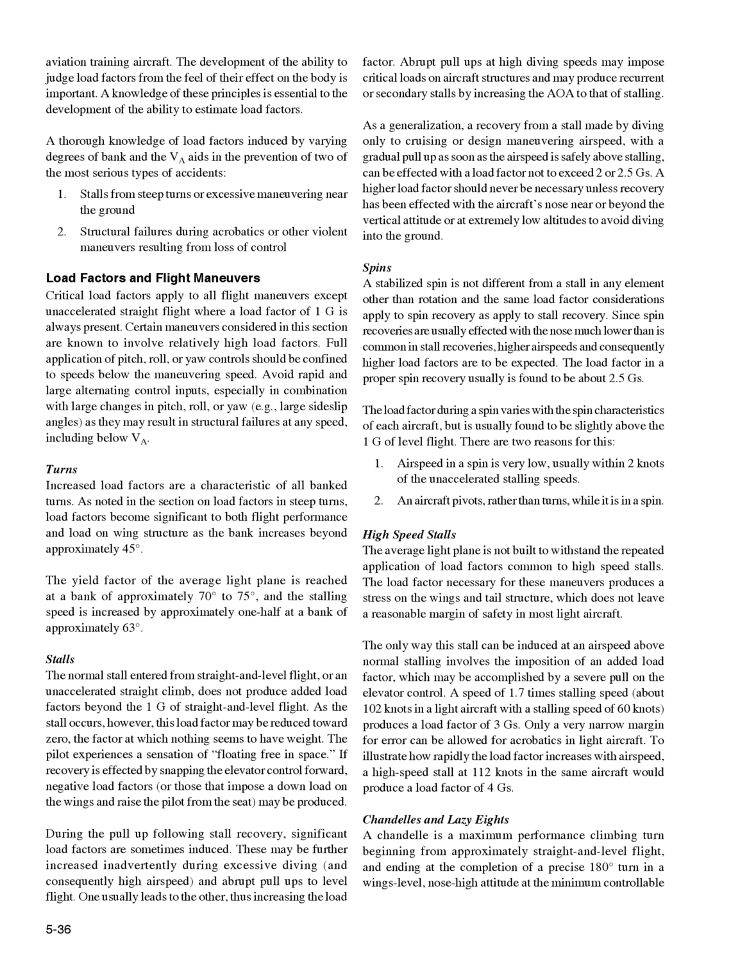Stalls. The normal stall entered from straight and level flight, or an unaccelerated straight climb, does not produce added load factors beyond the 1 G of straight and level flight. As the stall occurs, however, this load factor may be reduced toward 0, the factor at which nothing seems to have weight. The pilot experiences a sensation of floating free in space. If recovery is effected by snapping the elevator control forward, negative load factors, or those that impose a down load on the wings and raise the pilot from the seat, may be produced.